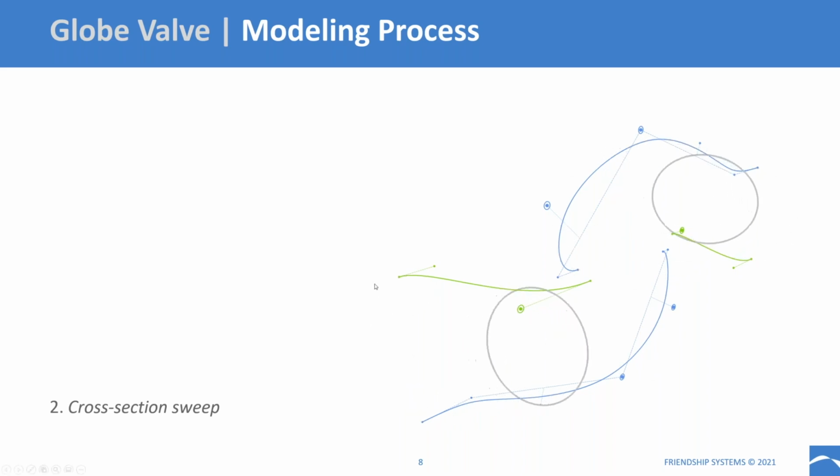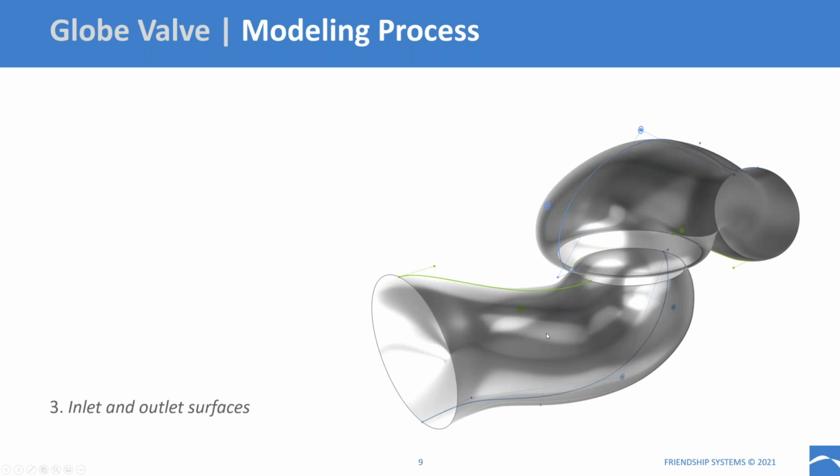And basically we sweep a point along the short contour and we sweep a point along the long contour and connect these two points with a circle or an ellipse, and that controls the vertical axis of the ellipse, and the horizontal axis is controlled by an aspect ratio parameter so that we can make these cross sections wider to the side. And this gives us surfaces.